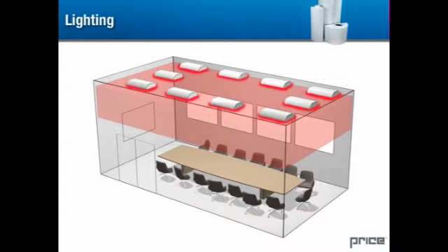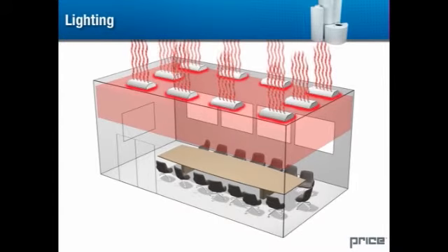A light fixture has a thermal plume, but because it's already in the upper zone, all of the convective loads will be in the upper zone. The radiative component of the lighting load will put a smaller load in the occupied zone as heat is transferred to all surfaces in this space.